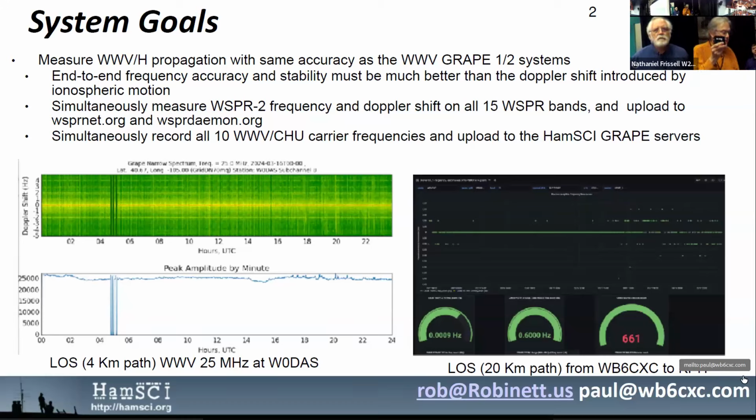This is a software-defined receiver module, commercially available from China for about $160. It has a 16-bit analog to digital converter that runs at up to 130 megasamples per second, although we run it at 64 megasamples. When combined with Phil Karn's KA9Q radio, it can process the samples that come from this and produce an almost unlimited number of receive channels.